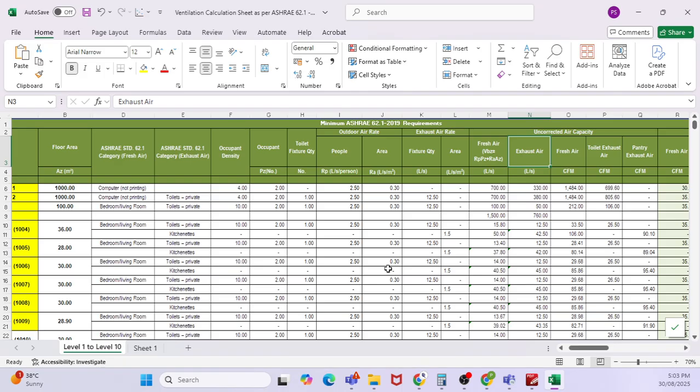Normally as the standard, you have 85%. Some engineers will apply 90%. Some engineers will apply 95%. Depends upon the contamination. If you expect more contamination, apply 85%, so that you have more positive pressure inside the space, so that the contamination will not come inside. If you see that your space is surrounded with less contamination, then you can go up to 95%, or you can go up to 100%.